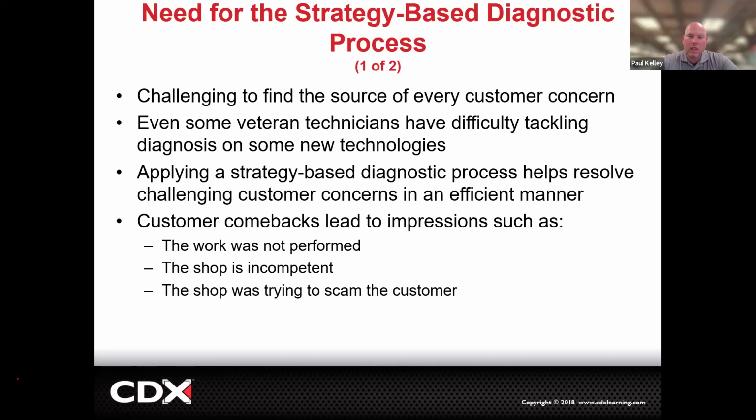It's a process of elimination, right? That's what it said in the previous slide. It's a scientific process of elimination, not replace one part, and if that doesn't fix it, replace the next, right? If I think it's the compressor, I test the compressor. If I think it's the thermal expansion valve, I test the thermal expansion valve. Make sense? Okay, and then additionally, if we get comebacks, customers are going to think maybe you didn't perform the